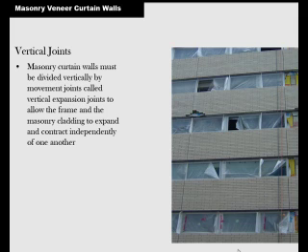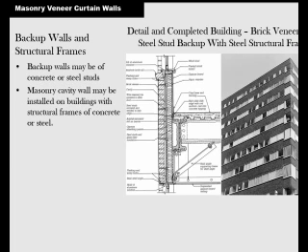Vertical joints in masonry walls are also needed to control the movement, and they're showing you some here. You can see them right there, and the architect will decide where those go so they look nice and don't just look thrown up there some way. Here's another good detail of a brick veneer with a steel stud backup. Here you've got your steel that's been fireproofed. It's got a fireproofing coating on it. You've got your trusses. You've got a concrete deck for your floor.